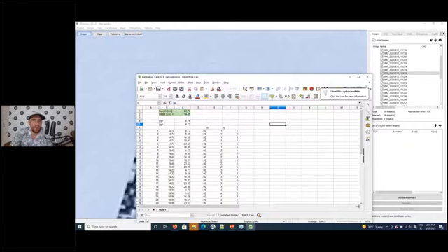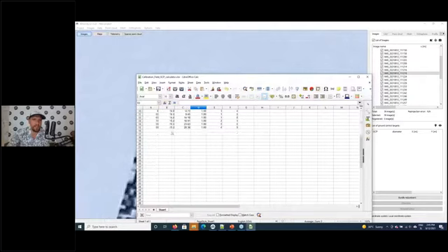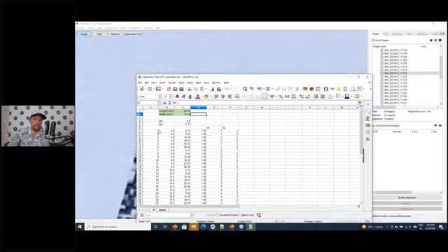You go here, you enter these two values. I measured it with the measuring tape, and this is in centimeters: 23.7, and here it was almost 14.2, so I assessed it to be 14.18. This will calculate the dx and dy distances, and when you input the value here, it will then calculate the coordinates of our ground control points in the field.